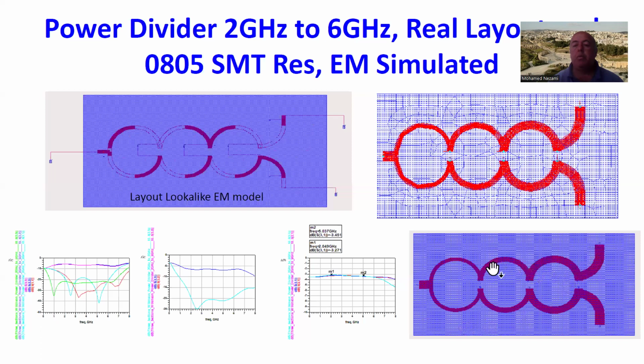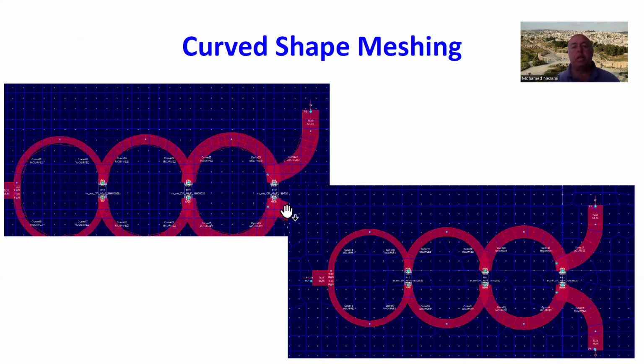And now we're not talking anymore about microstrip sections. We're talking about an EM model of the whole thing. And then we make a schematic out of this where this EM model is actually combined with the actual frequency response of these surface mount resistors. And then we sweep it and we can visualize the impact of that. It gives you more accurate results, and that's another way that you could actually predict the performance of the circuit when it's laid out.